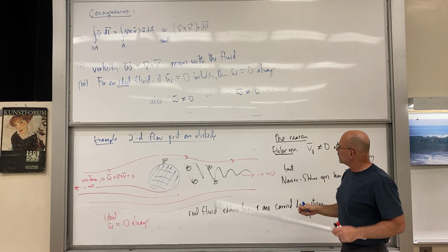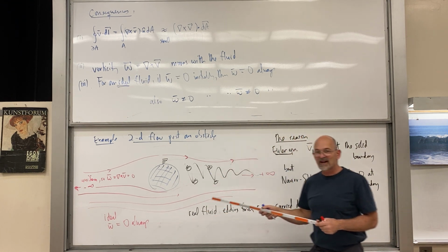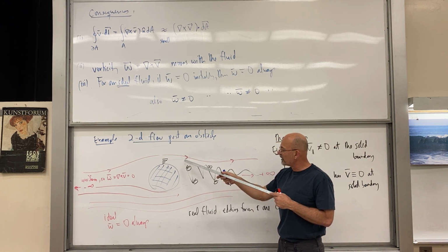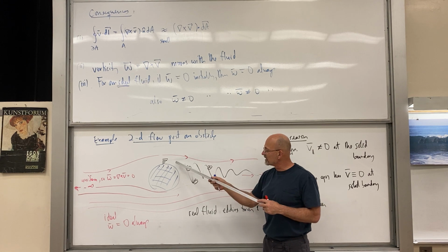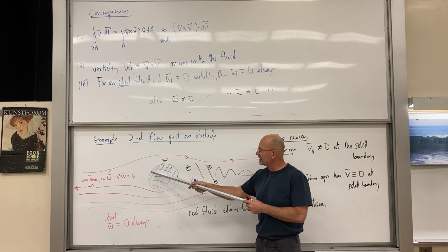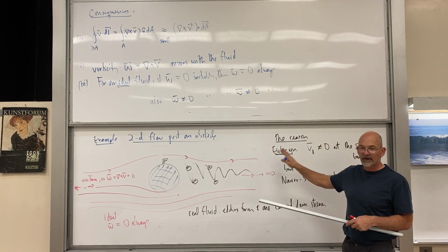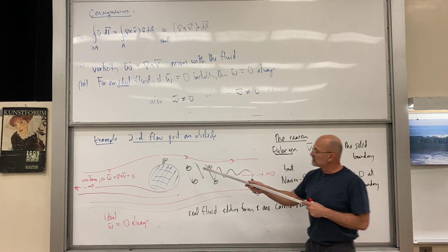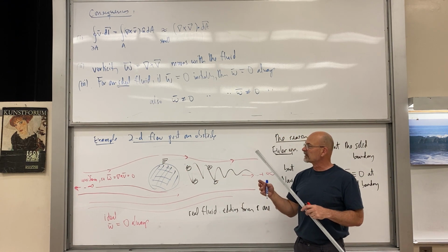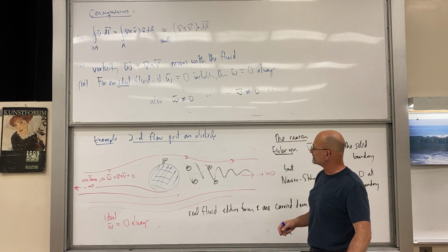So the ideal fluid has these interesting vortex theorems, but the actual generation of vorticity happens primarily at a surface. That's where it's easiest to do. It can happen anywhere in the sense that there is internal friction in a fluid, but you can generate them at a surface, and they can then propagate conserved, and that way they can propagate for a great distance in the bulk.